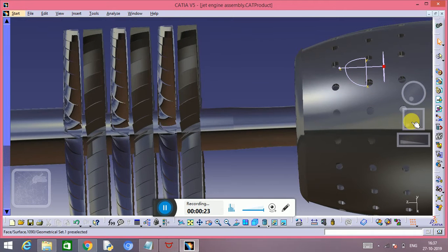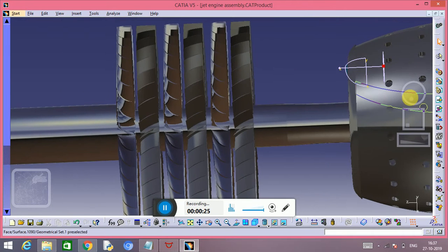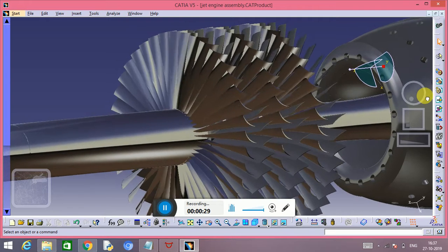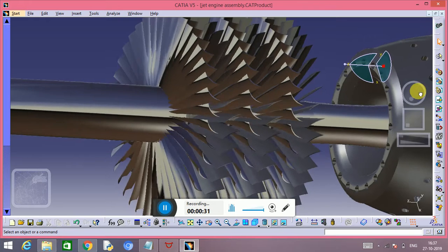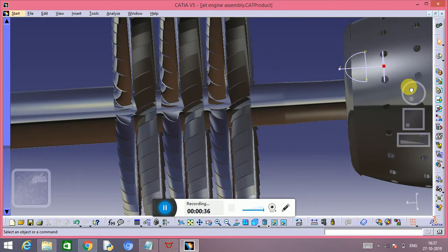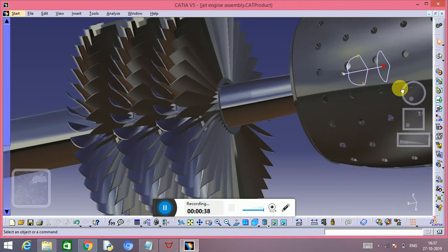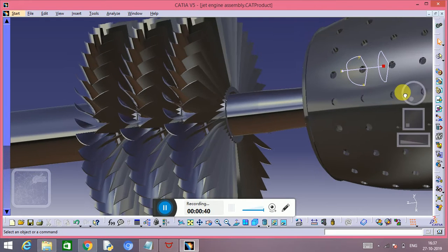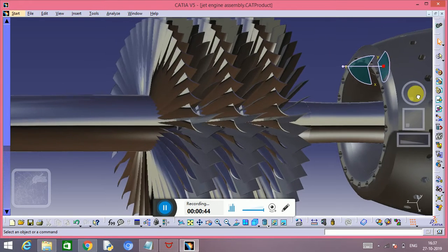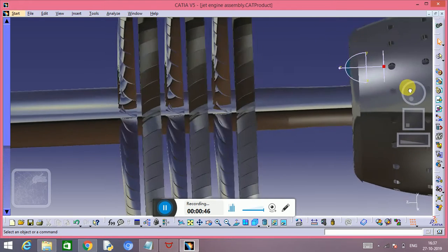Thereafter, the pressure of the air is further increased by the axial compressor turbine. This works in the same way as a moving fan, which has high pressure air on the front side and low pressure air on the back side due to the moving action of the fan blades. The design of the turbine blades is also such that it gives an optimum increase in pressure.